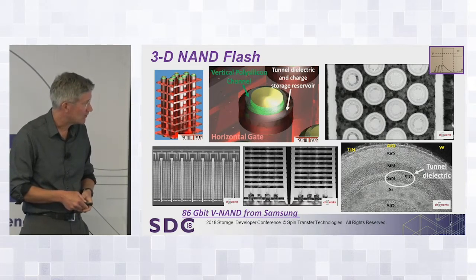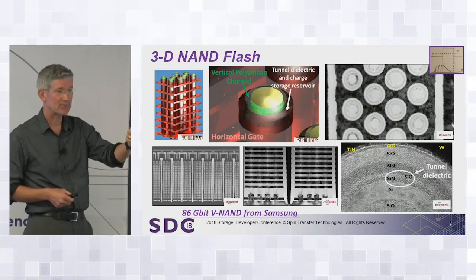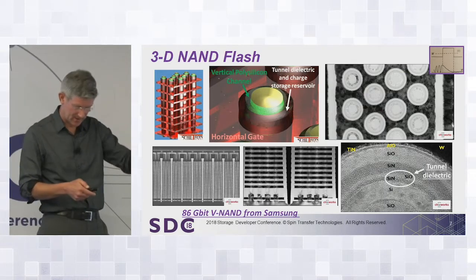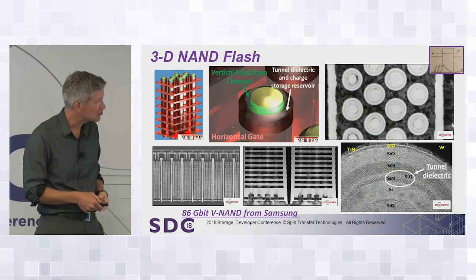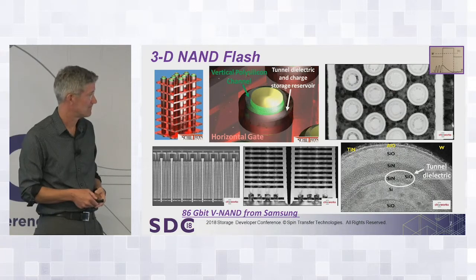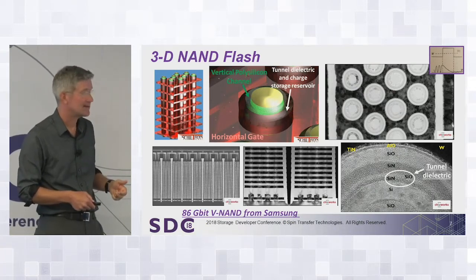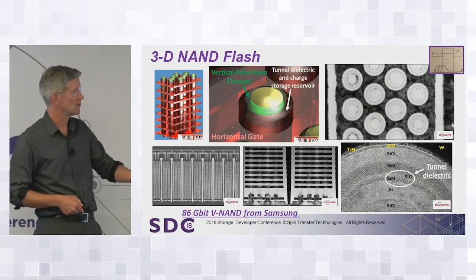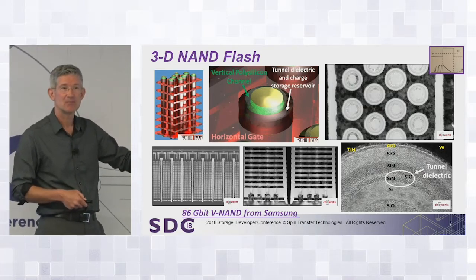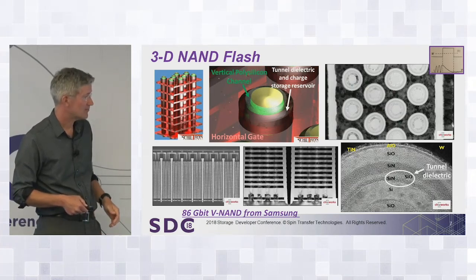And then we have the channel. So we have the field effect device, we have the reservoir for storing charge, and we have that tunnel structure to get the charge in and out of the reservoir. That's all it is. The rest is the engineering of putting that together in a way that leads to reduced cost per bit. But that's basically what it is. So the tunnel mechanism right here. You can imagine alpha particle decay right here.